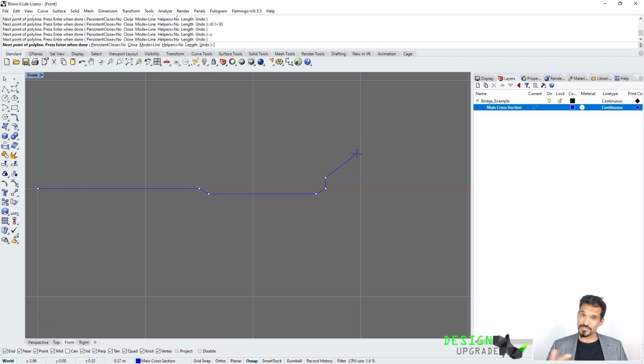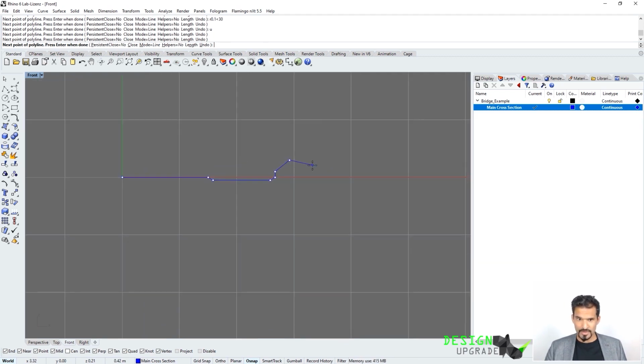So just have a nice view to whatever it is below the bridge. But we want to have that. And to do so, I want to have again a slope. This time I'm going to use relative coordinates. So R, yeah. I want to say 0 point 0.25, comma 0.2. And there you go. We already have our slope there, right?